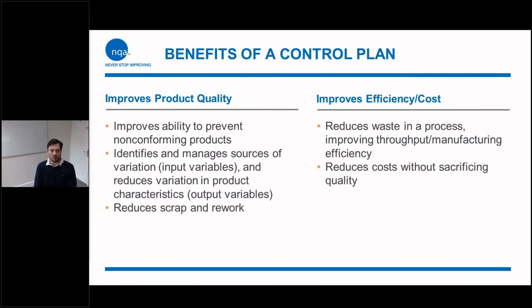So benefits of a control plan: they improve the ability to prevent non-conforming products, identify and manage sources of variation input, reduce variation, reduce scrap and rework, and can improve efficiency and cost, with less waste and less cost without sacrificing quality as well. Okay, so quality plans are quite good.